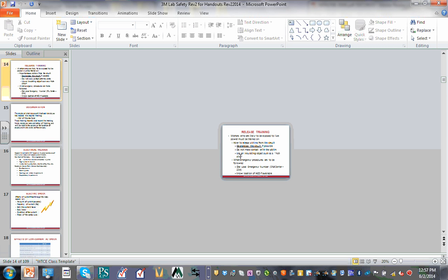A lot of times, especially on newer equipment, you have a label that will say your class. In the older stuff, it's usually based on the circuit connected to the building it's in, and what's in the next panel. So someone has to go through and do all those calculations for all of these areas. Usually, like in PNCS, the process electrical person will go through. When we put in new equipment, we calculate all of that and label it. Not everything is labeled because we have older equipment; either it's not labeled, or it's calculated somewhere and not labeled.